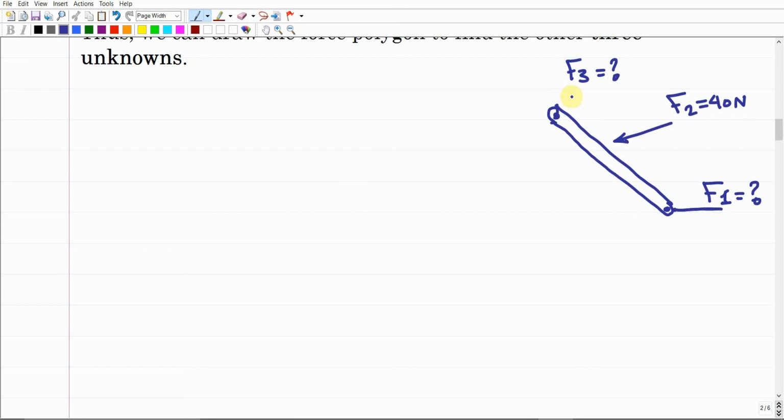So for this case, I'm just going to put it in this way. If I draw a force in this way, this indicates that this force is completely unknown. So for this membrane, F3 is completely unknown, but F2 is fully defined as magnitude and direction, as we used to do for the complex algebraic method for the position and velocity analysis, right? And the acceleration. The same thing for the F1. F1, we have no clue how much its magnitude is, so the magnitude is unknown, but the direction is known.